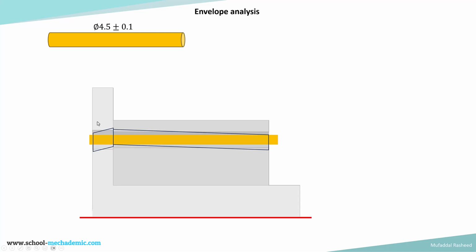Considering that the hole on part A is larger and the cavity or the envelope for the part A hole is much larger, we do not consider that to be the worst case. The worst case is the hole on part B, which is the longer hole, and the one which has the smaller dia. Hence that has to be considered for making the final envelope for the pin insertion.